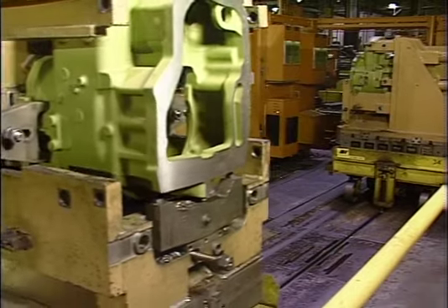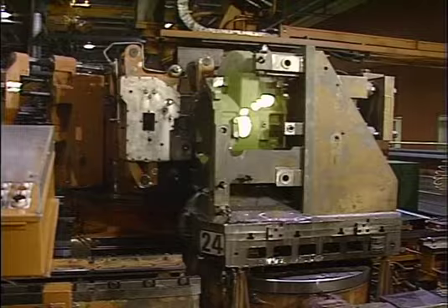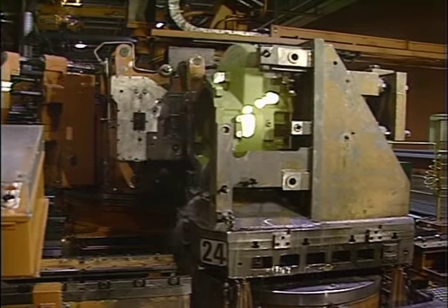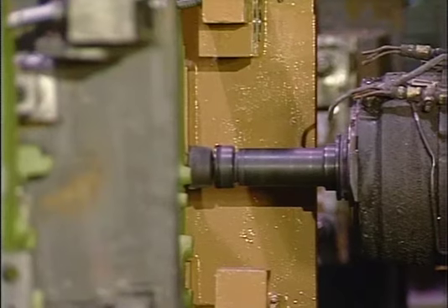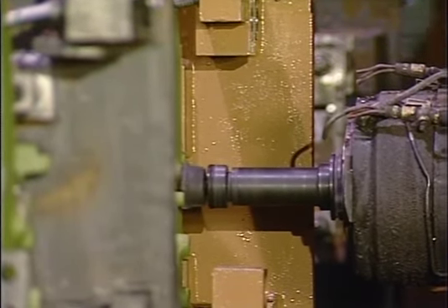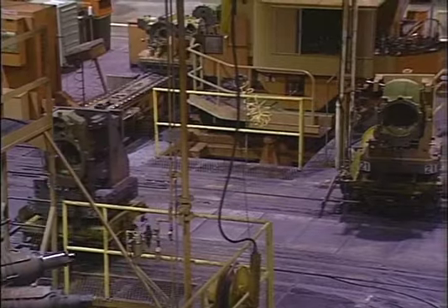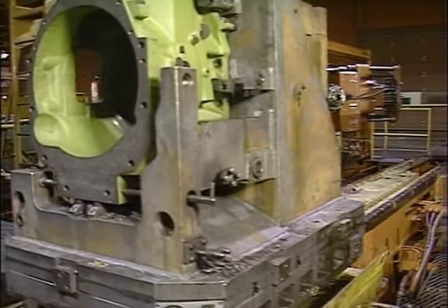FMS offers flexibility in the types of products that the system can produce and in the production rates. The machine centers are capable of performing several operations such as drilling, boring, grinding, etc., on different parts belonging to the same group technology family. Part programs and tool selection instructions are downloaded from the central computer to the machine center when the workpiece is delivered by the materials handling system.